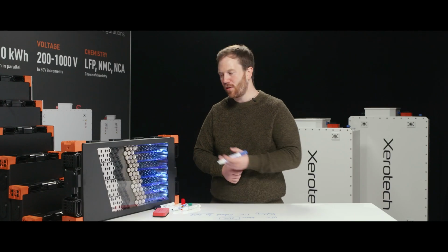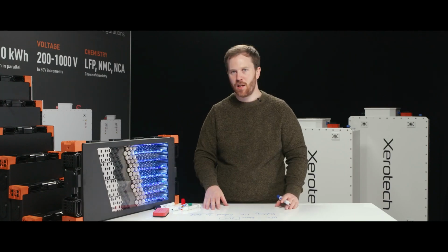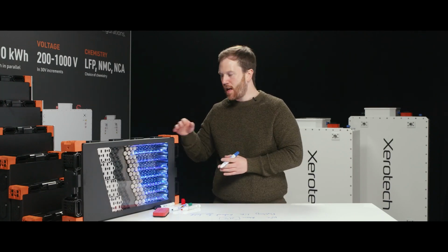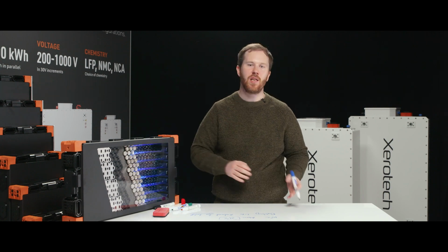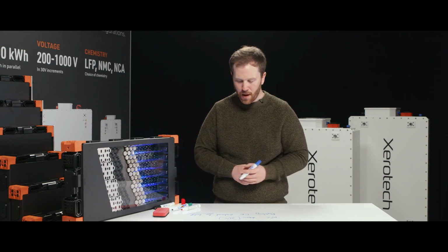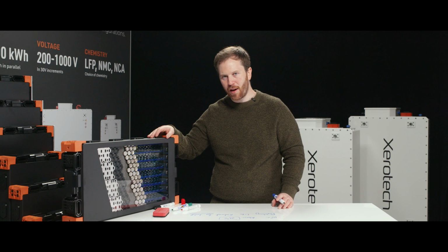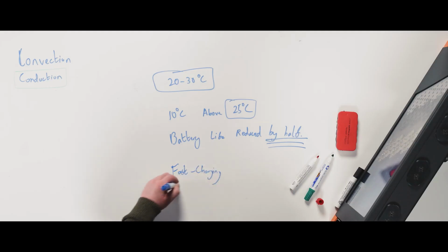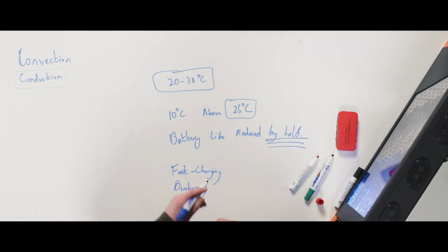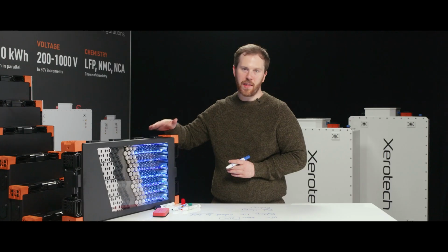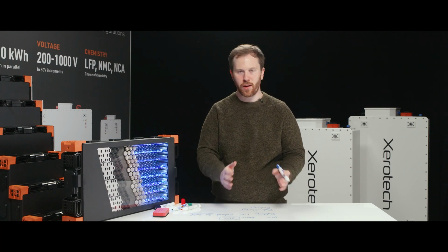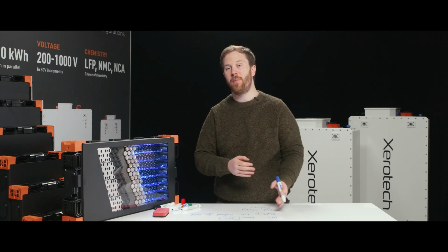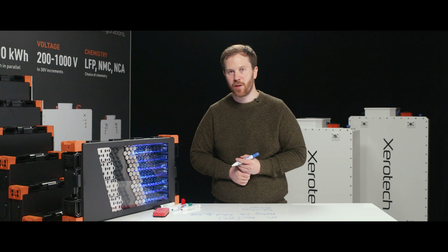So thermal management is really important for day-to-day use cases to increase the lifetime of the battery and decrease the total cost of ownership. But also for high-performance battery systems, it's mandatory. If you're fast charging or doing aggressive discharging, you're going to be generating a lot of heat. So you have to get that heat out, and the only way to do that is with a thermal management system and probably some form of liquid thermal management system.